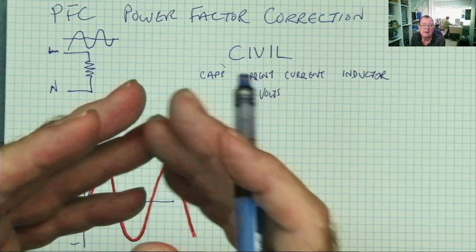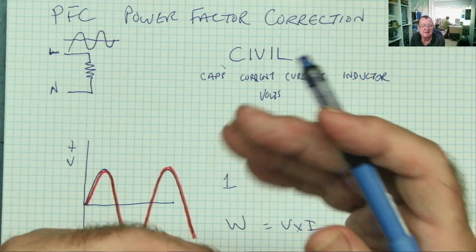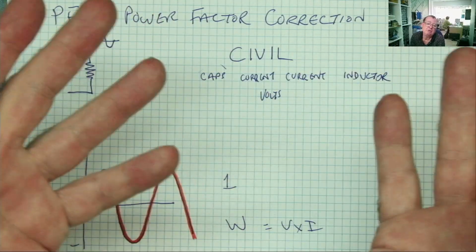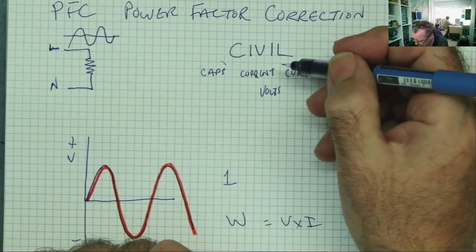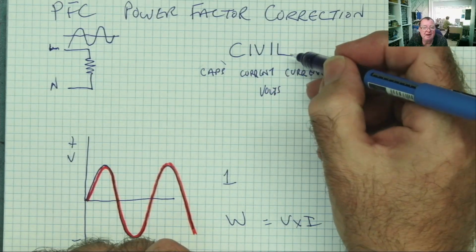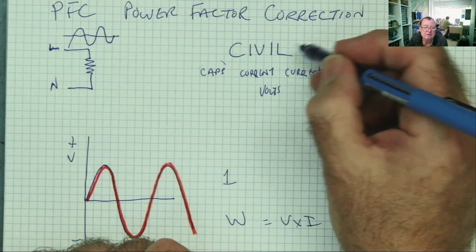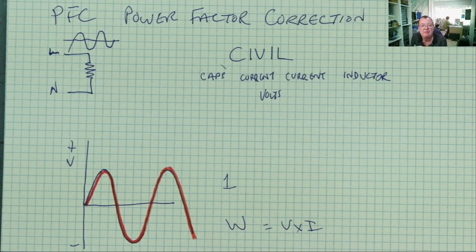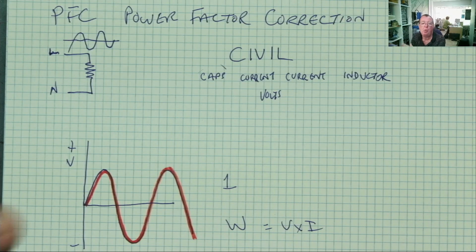This makes sense. When we charge a capacitor, before we can get any voltage across the capacitor, we have to put current into it, yeah, because it charges, okay? The other half of this, VIL, voltage leads current in inductors. This is not quite so intuitive, but basically with an inductor, it has inertia, like a water wheel.